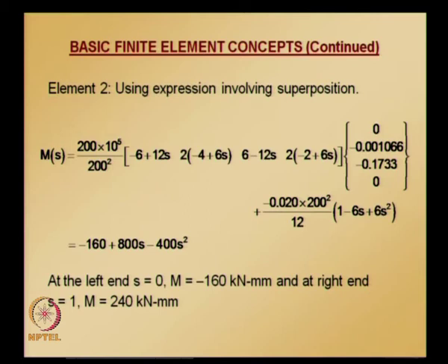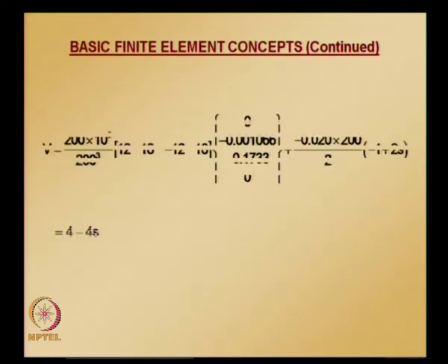And please note that we will be drawing the moment using these values, we can draw moment and shear diagrams for the entire half model. And shear for the second element is given by this, again the first term is the finite element interpolation and the second term is the fixed end shear corresponding to a uniformly distributed load.